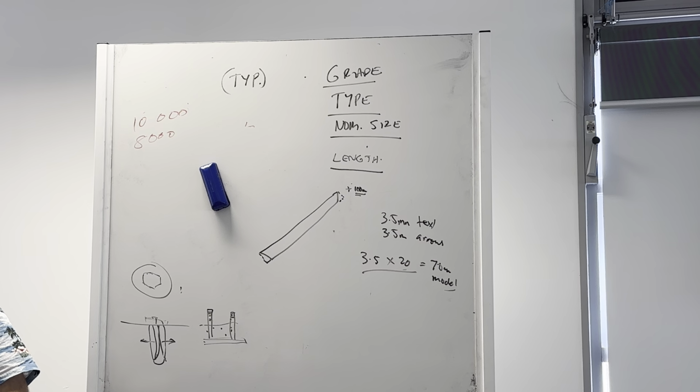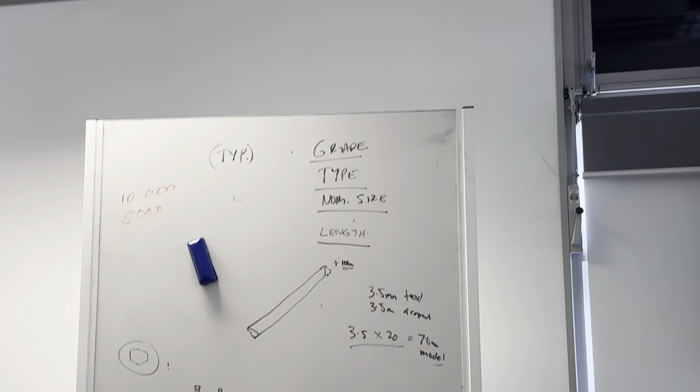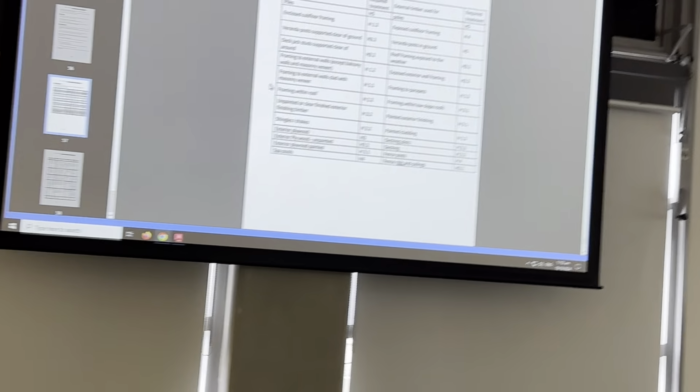And then you get down to H1.2, which is your timber framing, and you're hoping that that framing is only exposed to weather for a short period of time. So it is weatherproof for 3, 4, 6 weeks, and then you're hoping they'll close the building in at that point, okay? At one stage in New Zealand, they dropped right back to non-tannalised timber for framing, and we got the leaky home syndrome.